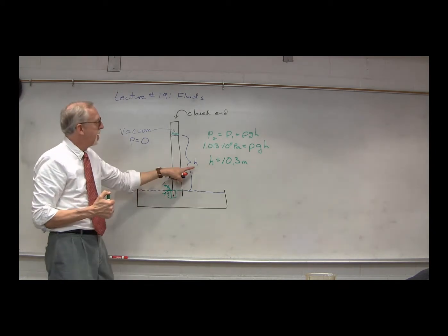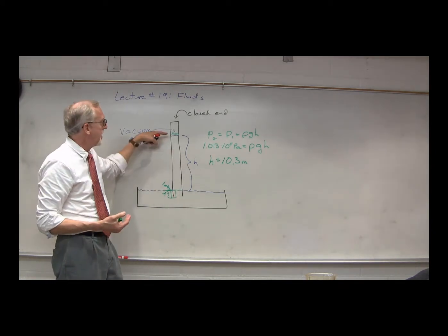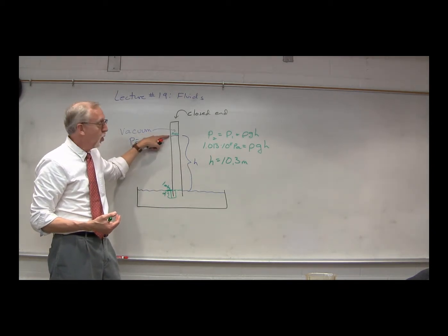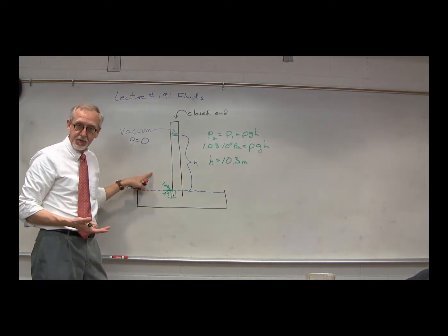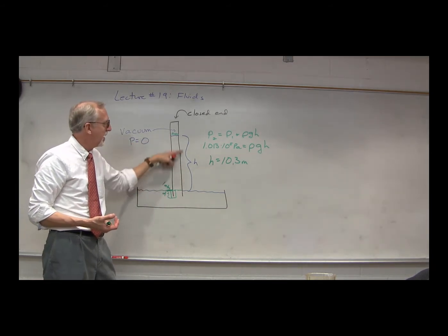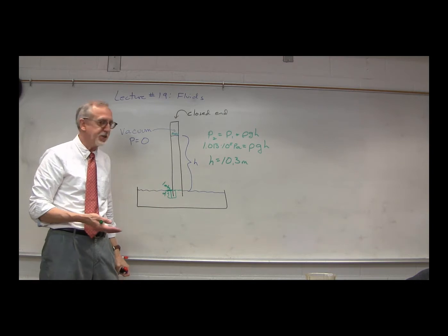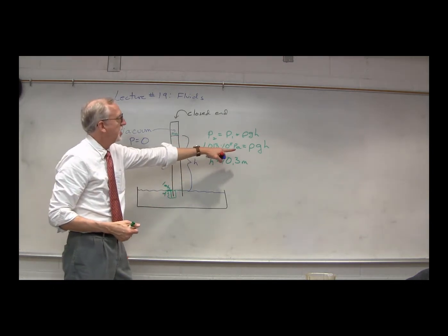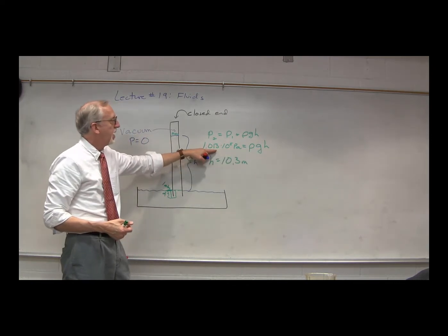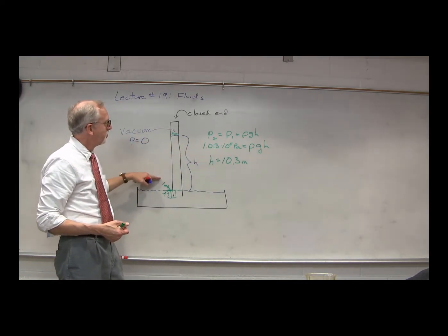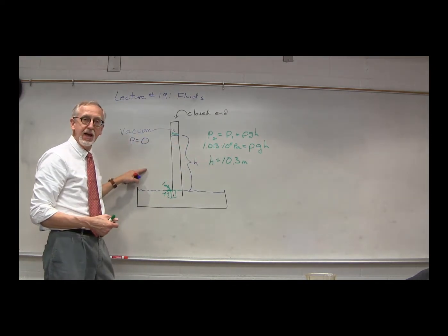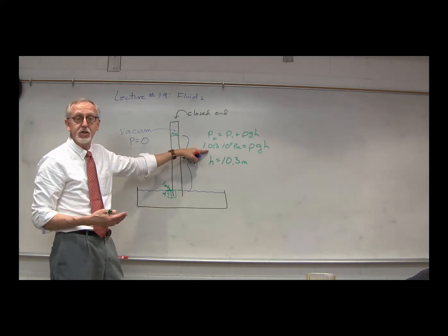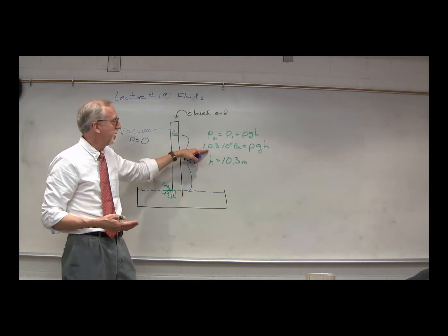And then, by measuring any fluctuations in that height of the water, we'd be able to determine what the atmospheric pressure was. This would be a way of measuring atmospheric pressure, by measuring what that height is, and then putting in h, take rho g h, and figure out what the pressure is, and that would tell us what the pressure was out here, if atmospheric pressure varied from the 1.013 times 10 to the 5th.